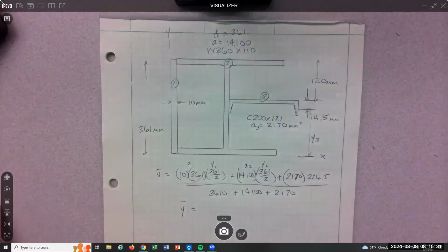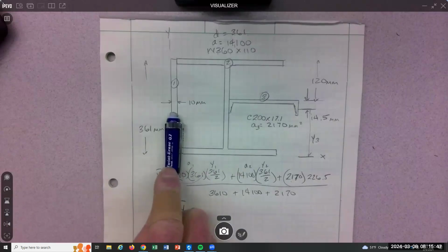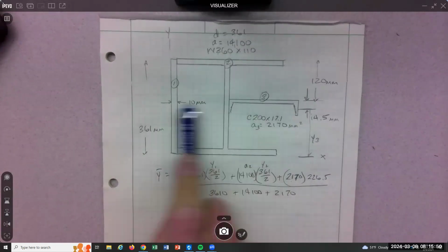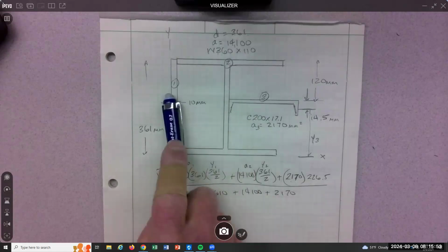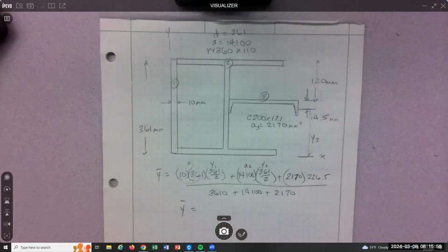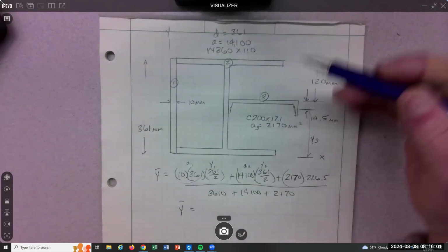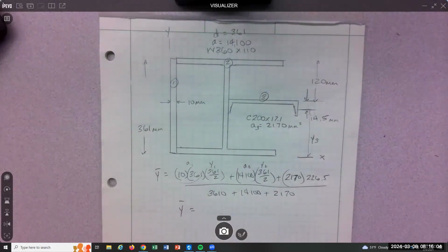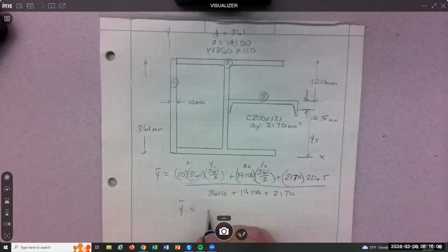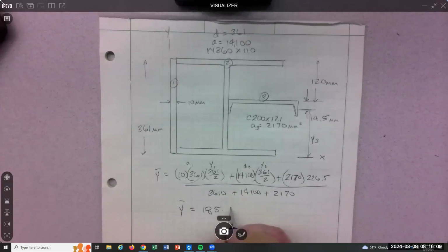What do we get? I'm guessing, let me guess. We're halfway up is one, half of 361, 180.5. This doesn't do anything to the location of the composite, like the eye shape and the plate. They're lined up, right? So then none of that. So then this 120 shifts it up a little. It's gonna be like what? 190? What'd you get? 185. 185.52.